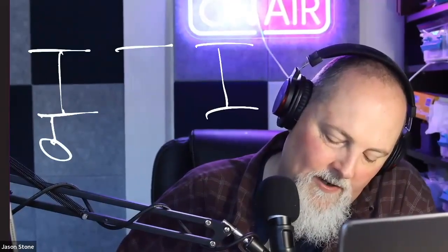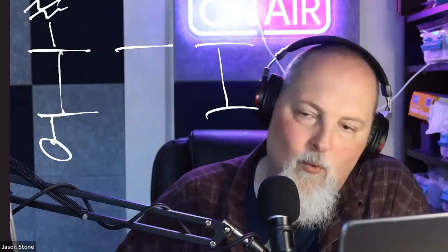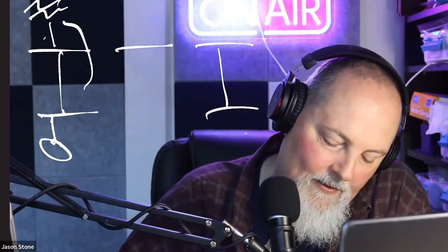Interlocks. So the other thing we have are interlocks. An interlock isn't similar to an isolation, an actuation, or a scram. An interlock is a way of protecting equipment by preventing things from happening that shouldn't happen. For example, if we go back to our SM1, SM2, SM3, down to our SM7, SM8, if I started up the diesel generator on SM7, DG1, and we still have power from our main transformer, I don't want those two to be tied together.